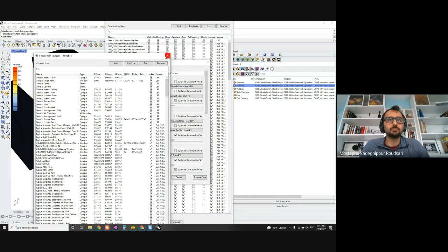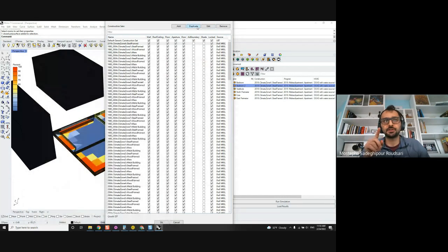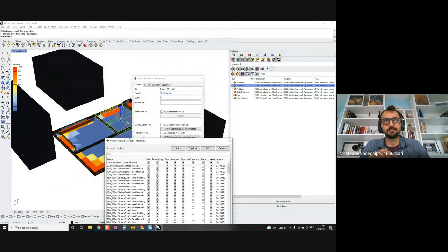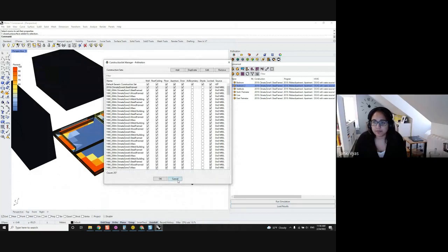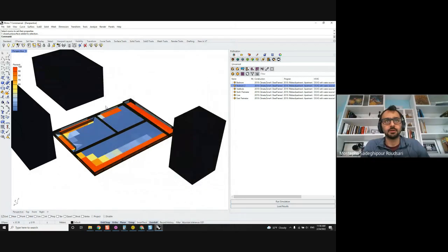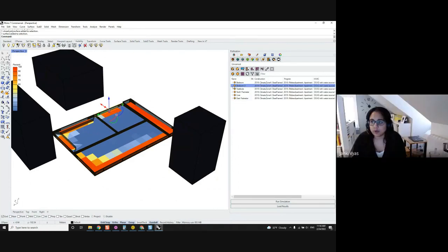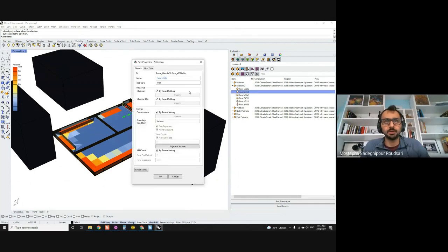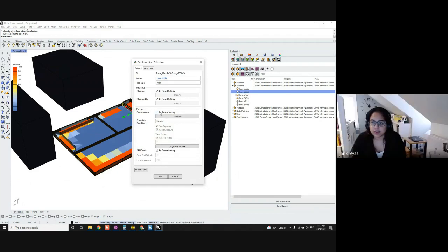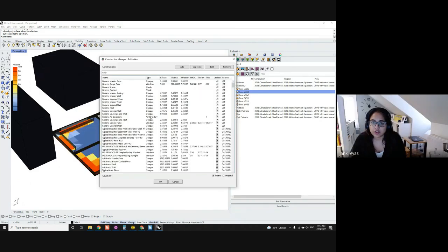Right, I think this question mostly is about just selecting a surface and editing the parameters for that surface, not the room. Yeah, for the surface itself. So if you select the surface, you can select it from that drop down too, or I can show it here if you want. So if we go to a room and we select a face, a face with a window, here's similar. The construction setting, so you can change it off the parent setting and change it here.